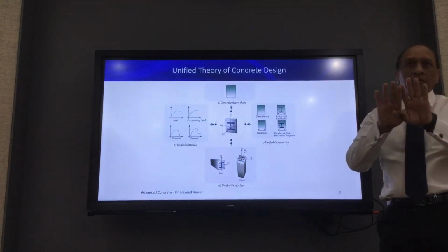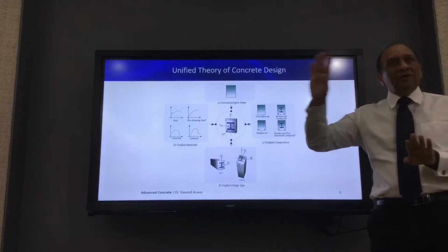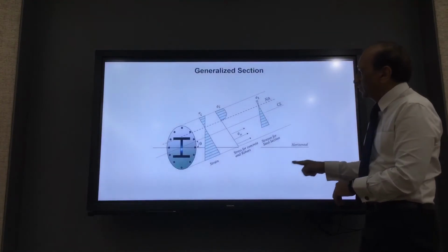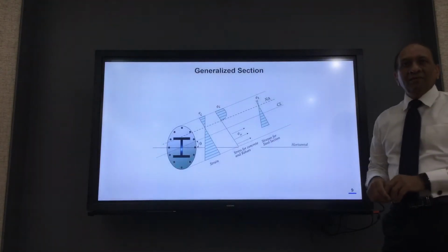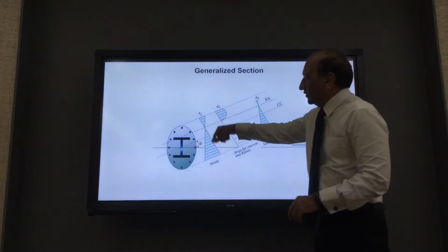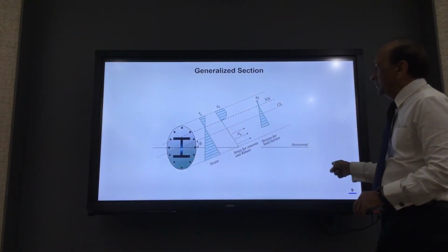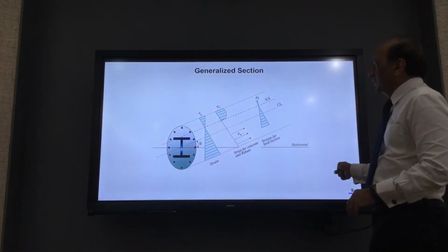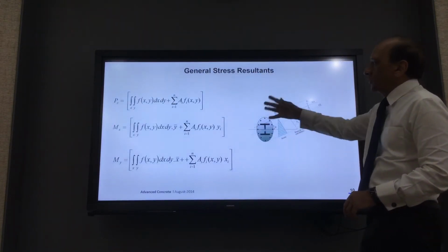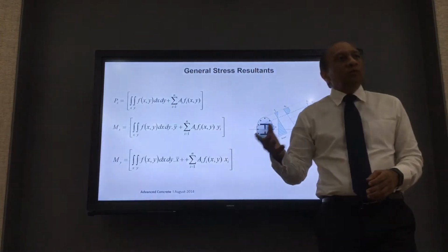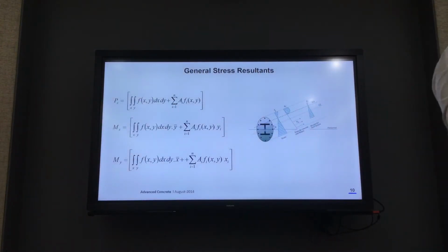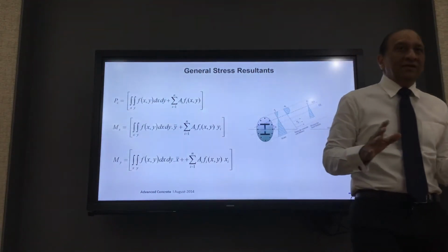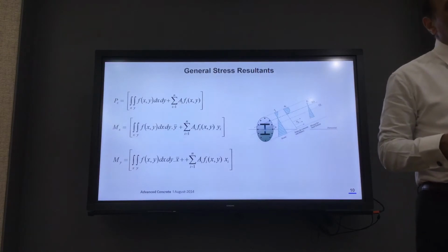And at that time, we talked about two phases. One was about capacity, the other one was about moment curvature. And now we are talking about the second portion, which is about moment curvature. So you remember this diagram, right? We developed a theory that will handle any cross-section for any deformation. So we are starting with the material, known material and known strain configuration, and then we use these equations to predict the response and also to predict other things like moment curvature and many things that you have seen in the last course. So what you studied last course is very, very important for doing PBD or going forward with that one, okay?